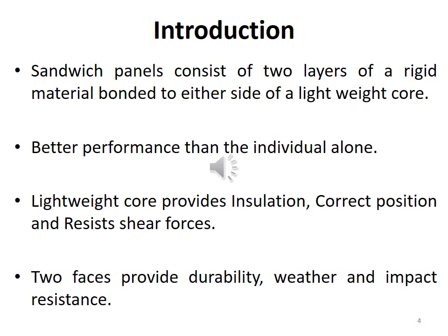The idea is to use a light or soft but thicker layer to serve as a core, and strong but thin layers for the face sheets. This combination results in the increased overall thickness of the panel, which often improves the structural attributes like bending stiffness and maintains or even reduces the weight.